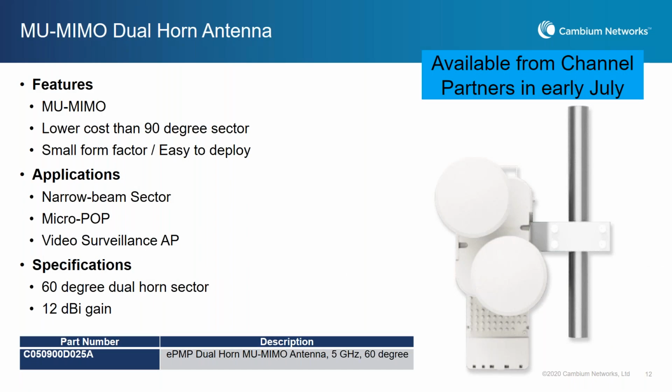Oh yeah, in fact, here it is. So it's a little better picture of it. Horn antennas are nice because they give you a narrower beam. This one is a 60 degree. And it also has the benefit with a horn of having reduced front to back ratio and reduced side lobes. So you're really pushing all of the energy forward and into a tighter pattern.